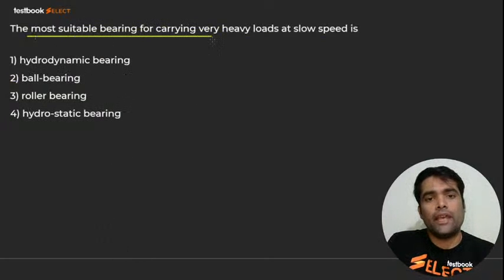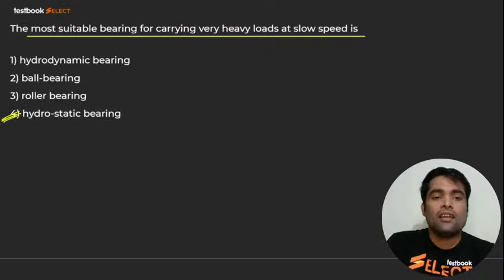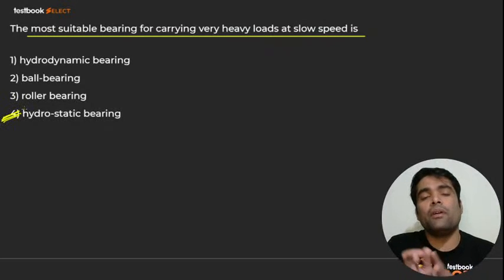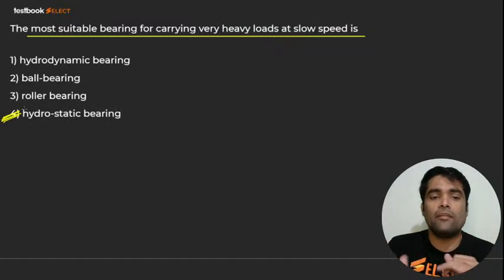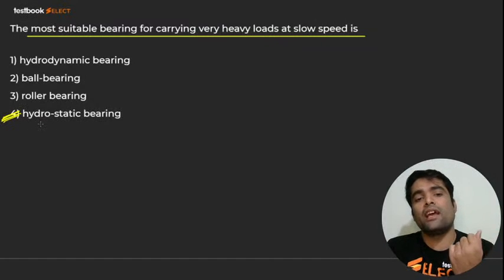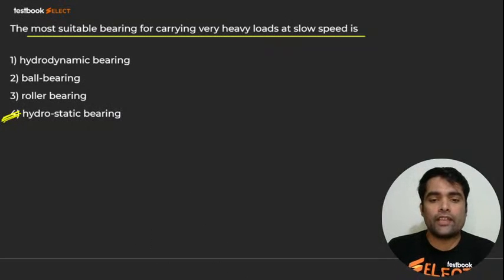The most suitable bearing for carrying very heavy loads at slow speed is what, my dear? Nothing but hydrostatic bearing. Because there is no relative motion between what, my dear? Journal and bearing. Between journal and bearing there is no motion, so that's why we are utilizing this one. Okay, here I go for next, my dear.